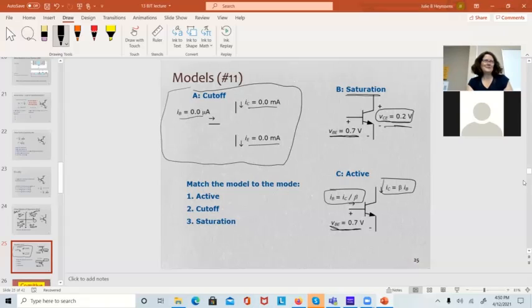And what I would do on one of Bagensky's tests, and they were horrible, he typically failed about 2/3 or more of the class, is I would write down, if I knew it was in saturation, if it was a digital circuit, I'd make all my VBEs 0.7, I'd make my VCEs 0.2, and then I'd figure out the rest of the circuit. And that was the thing that got me through it.